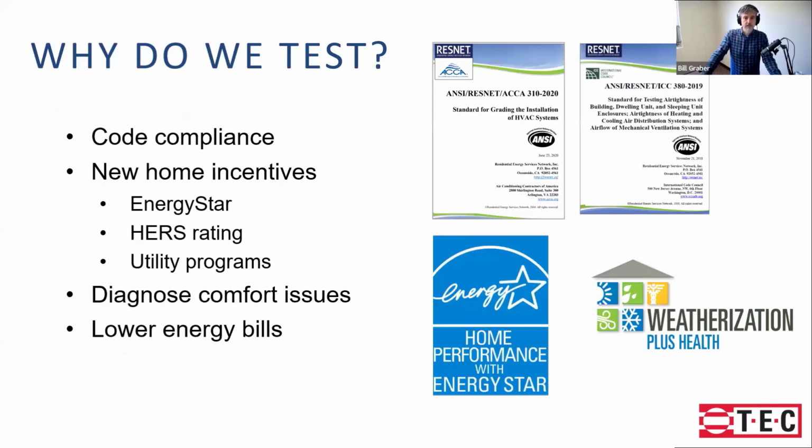Why do we test? There's a lot of reasons that we do these tests. Code compliance is a major driver of this. There's also a lot of different programs that require testing the ducts and having a certain standard there. But it can also be used to simply diagnose comfort issues. Ducts can be a major source of energy loss and comfort. And then overall, any duct sealing we do lowers energy bills, which is good for everyone.